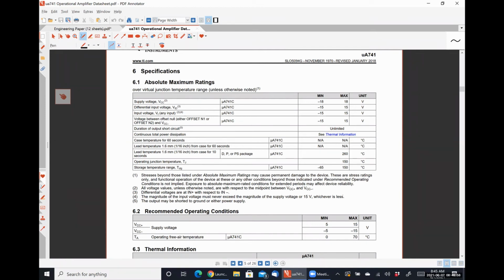I've seen students using LTSpice improperly set things up to where VCC plus and VCC minus are actually the same voltage, and then they don't understand why it doesn't work, and it's because you have zero linear range inherently, if VCC plus and VCC minus are the same thing. That's a fantastic question. We'll have example problems in the homework assignment that you're about to be assigned where the supply voltages are not equal and opposite. And that is going to obviously alter your linear range, and it's also going to alter the shape of your output signal, right?